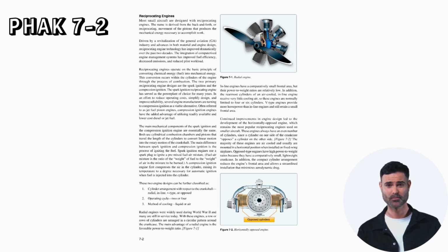The name is derived from the back and forth, or reciprocating, movement of the pistons that produces the mechanical energy necessary to accomplish work. Driven by a revitalization of the general aviation (GA) industry and advances in both material and engine design, reciprocating engine technology has improved dramatically over the past 2 decades. The integration of computerized engine management systems has improved fuel efficiency, decreased emissions, and reduced pilot workload.